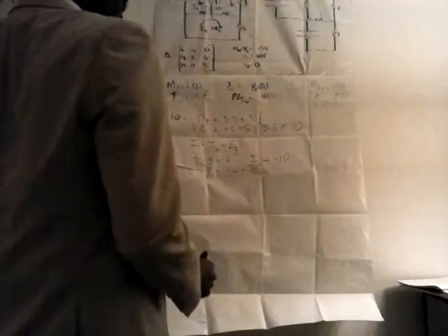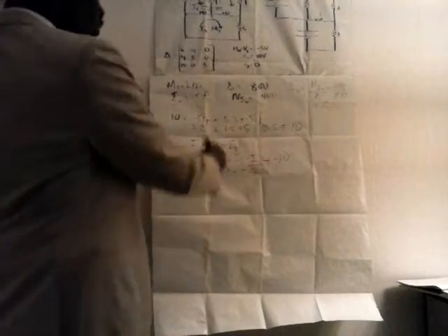So now we're finding it by KVL and KCL there, by taking it around the loop. And so we got 2 equations here and 2 unknowns. And so we could solve for I1 and I2 via the KVL and KCL and see what we come up with. And then we plug it back and see what amperage we get for it. So that is just a method of rechecking. And I've given you the principle of it.